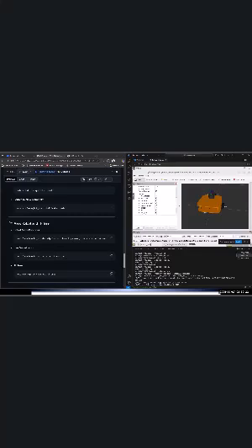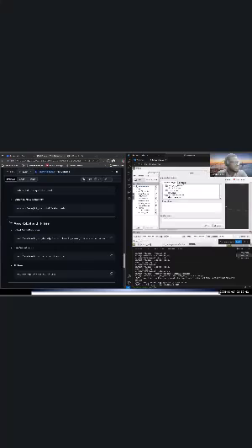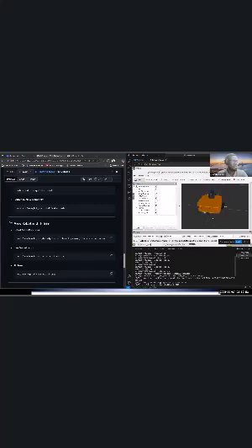Perfect, that's correct. Thank you for the answer. RViz means ROS visualizer. It's basically what we use to visualize sensors, TF, frames. If I want to visualize something, I see the available topics I can visualize. But when we launch the robot in Gazebo world, we're able to see more topics like the LiDAR, the scanner, all of that. So we'll see everything at work, don't worry.